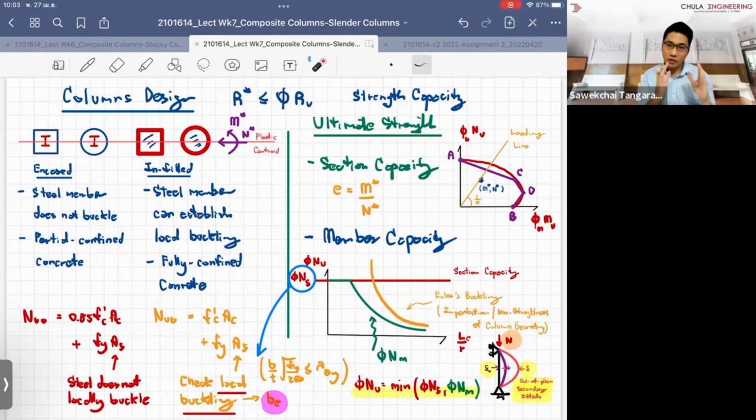It depends on whether you want to have the pure bending force. You take the sum of the axial force to be zero, because in pure bending, or when we design the slabs or the beams, we just talk about the pure bending conditions. But when we talk about the column, it has to come with a combination of the axial force and also the bending moment. Of course, we have to determine where the axial force should be applied.